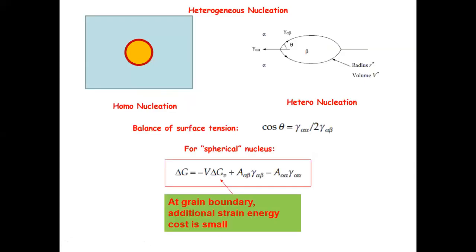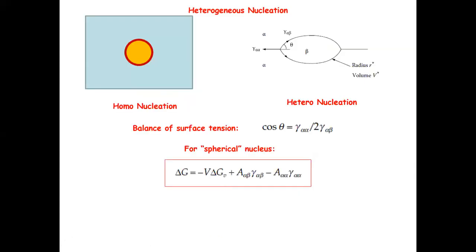As in the case of heterogeneous nucleation in the liquid-solid transformation, what we're interested in is to compare how heterogeneous nucleation reduces the energy barrier for the system, and is there any relation between homogeneous nucleation and heterogeneous nucleation? The interesting thing about why I'm still mentioning this is that the shape of the embryo is different in the solid transformation case than in the liquid-solid transformation case. In the liquid-solid transformation, we have half of this, just one spherical cap.